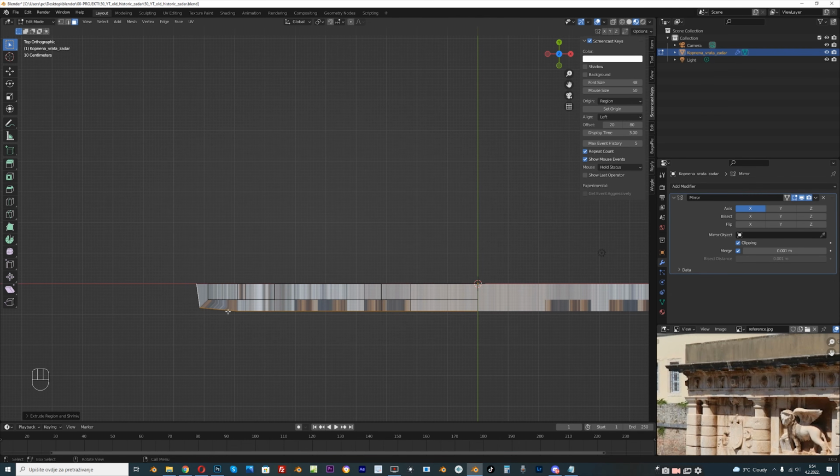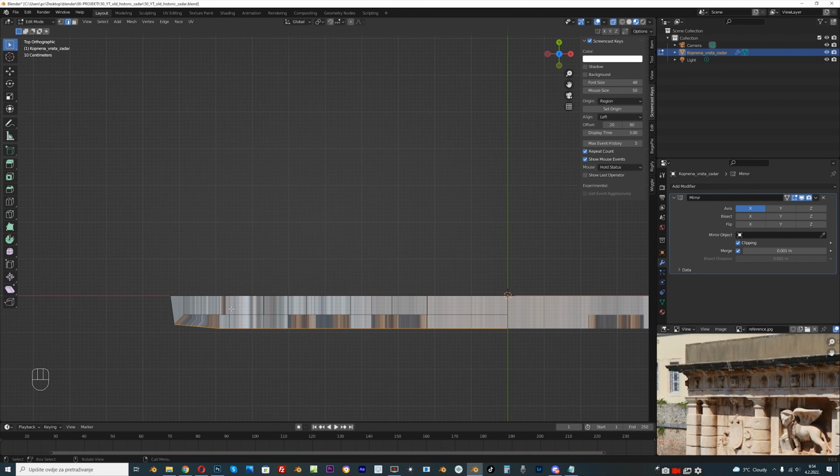And you can see that this line is not straight, so just go to wireframe mode and select this and press SY0 to scale along the Y-axis to 0, and select this line here and press SX0 because this is the X-axis.